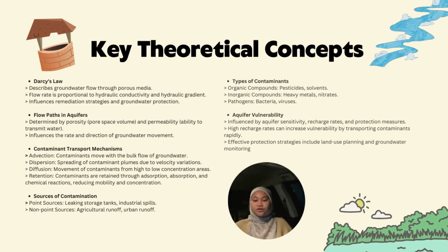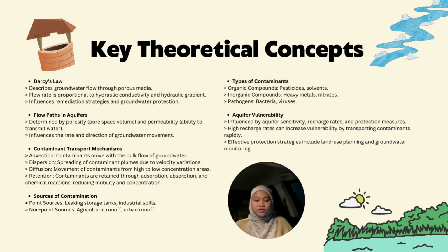For the key theoretical concepts, the first one is Darcy's law. It describes groundwater flow through porous media. Flow rate is proportional to hydraulic conductivity and hydraulic gradient. It influences remediation strategies and groundwater protection. And the flow paths in an aquifer are determined by porosity and influence the rate and direction of groundwater movement.